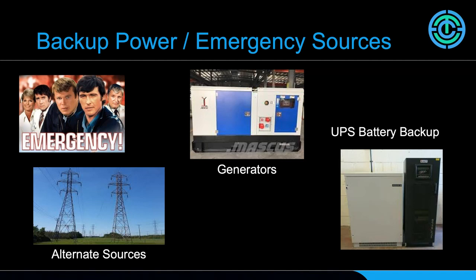It's important for this to maintain our systems, but it's also important to understand what we may be limited by once we move to emergency power. You'll be stuck with wattage limitations on your lighting systems or your sound systems. You may lose critical components when there is a transfer from normal power to emergency. And power planning is key in any integrated system.